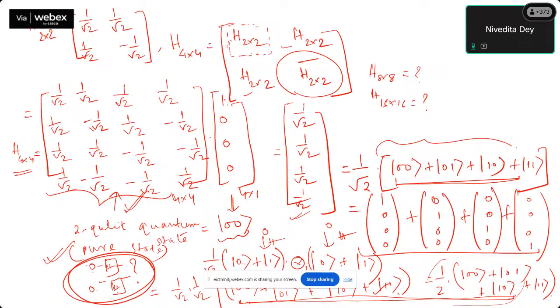So I got one question: what do I mean by 1000 for 00? I guess someone asked this about half an hour before; I missed it, sorry. So 1000 represents that the one is the indicator that it has to be high for 00. Similarly, 01 will be 0100. For 10, which is 2, it will be 0010. For that value position, it has to be on. And for 11, it will be 0001.